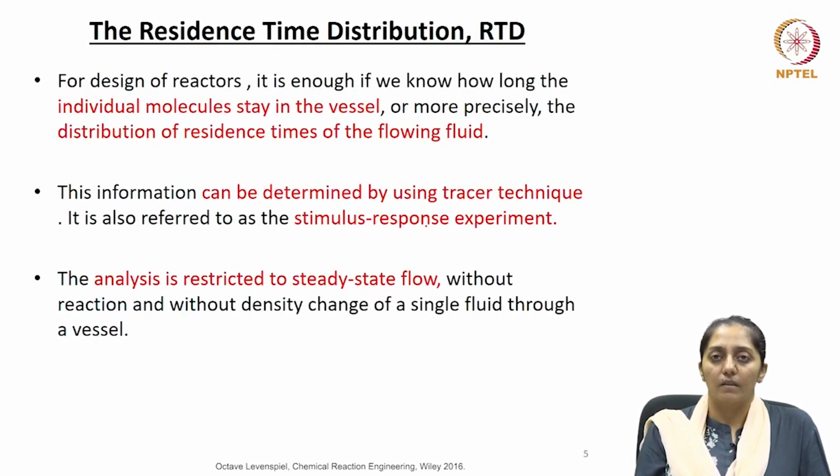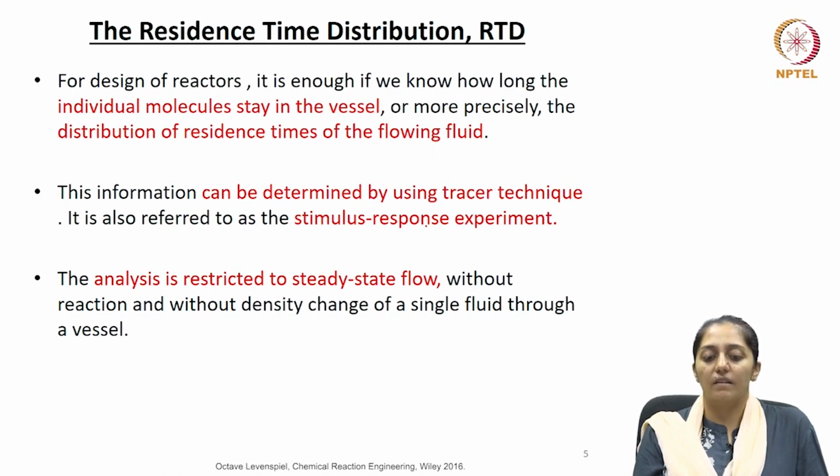So let's talk more about residence time distribution. Now for designing the reactors, it is enough if we know how long the individual molecules are staying in the vessel, or more precisely, the distribution of the residence times of the flowing fluid elements. Now, this information can be determined by using tracer techniques. It is also referred to as stimulus response experiments. The analysis is restricted to steady flow patterns without reactions and without any density change of the fluid through the vessel.